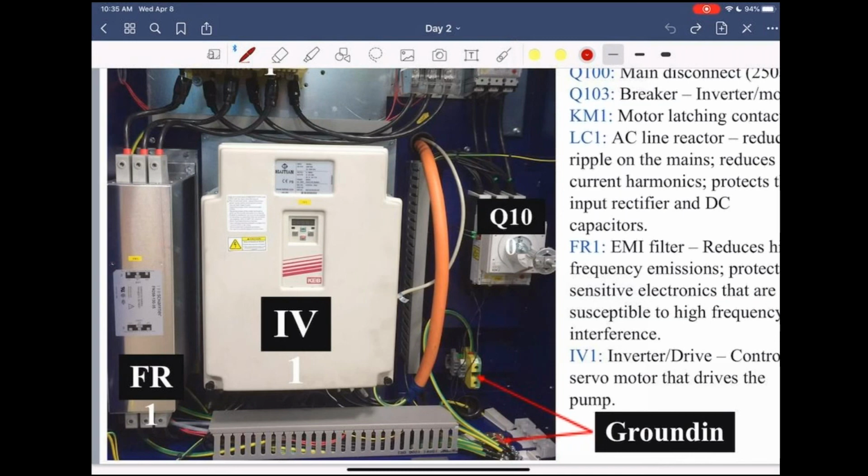Down here at the bottom, you have a grounding strap. It is recommended that you use a grounding rod at the machine because the voltage going through a bus system with your ground usually picks up noise. And what happens is the KEB driver relies on 0 voltage, and it gets 0 voltage from the grounding strap.